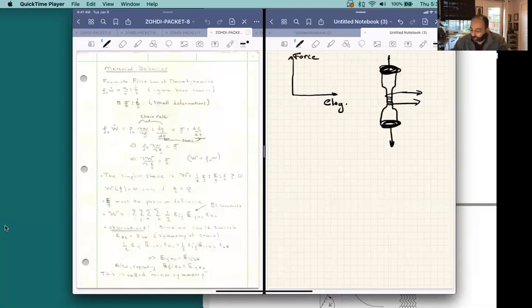Now, depending upon how fancy you get, these elongations could be in the form of strain or some other measure. And the concept of force could be anything from the second Piola-Kirchhoff stress, which we introduced all of last week, or the Cauchy stress, but there's going to be something that post-processes force to usually become force per unit area. It might be the current area, the actual area that's being deformed. It could be a reference area, but it'll be some type of normalization in this regard.